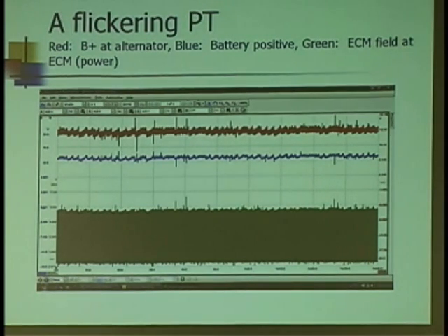But when I plugged my scope in and I got voltage, that kind of clued me in that the schematic and my service information was incorrect. That ever happen? A little bit. Once in a while. Several times a week.